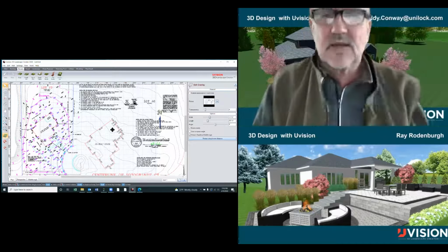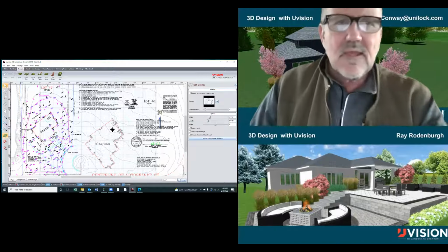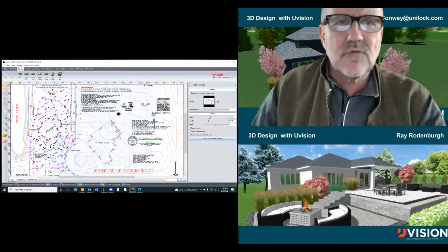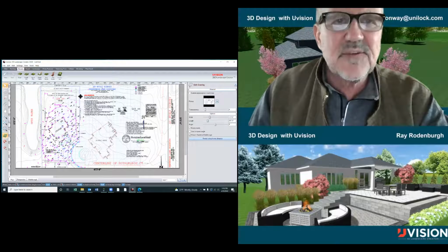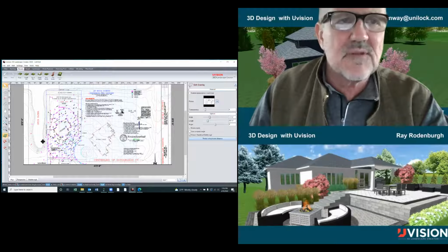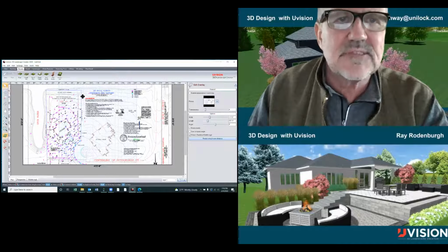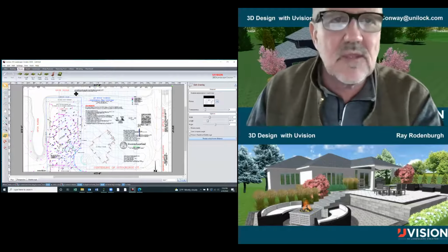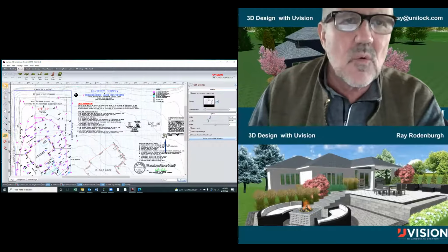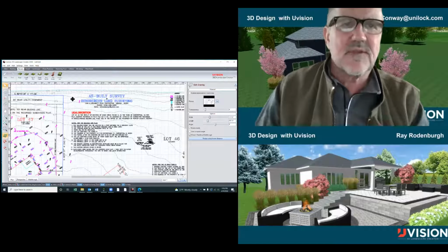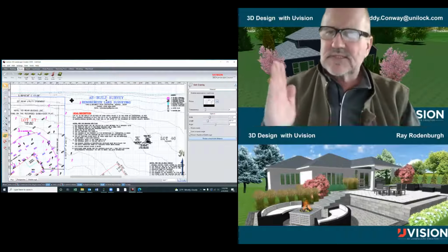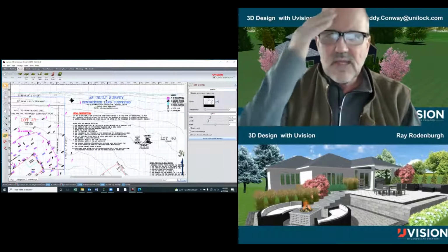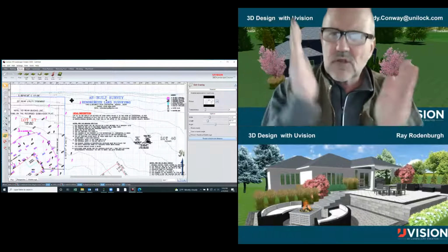Now here comes the ugly bit. Here are your contours. And we've said 672 is down here. There's water. You see this water path here? And I'm reading 670, 671, 672. Now you see, in surveying terms, when contours are close together, like you see here, that means it's steep. The closer they are in plan, the steeper the climb.